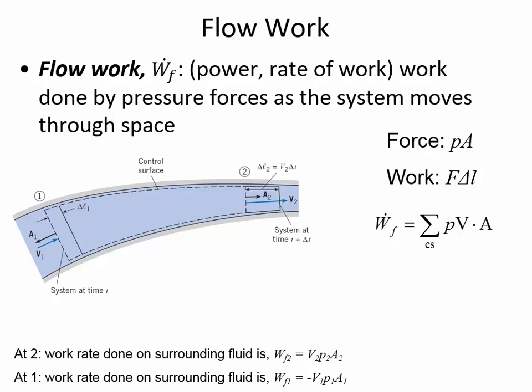And what we have to remember is that there's friction losses. As the water flows through the pipe, the pressure is going to be decreasing because of the pipe friction. And so you can think of that as work that the fluid is doing on the pipe itself. There's different ways to account for it, but you can think of the loss that you're experiencing in pressure as because of the work that the flow is doing.